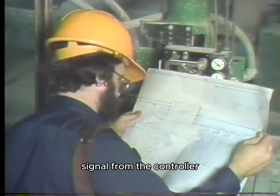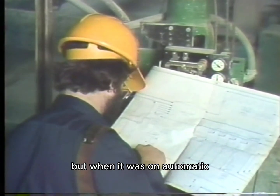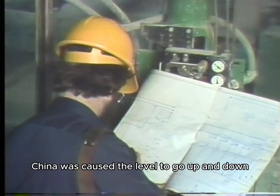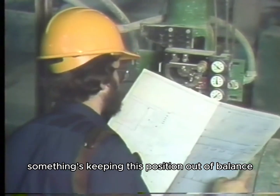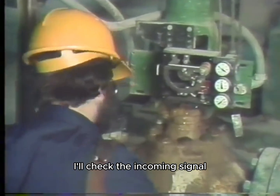The signal from the controller and transmitter was steady when the system was on manual, but when it was on automatic, the valve started cycling, which I know has caused the level to go up and down. Something's keeping this positioner out of balance. I'll check the incoming signal.